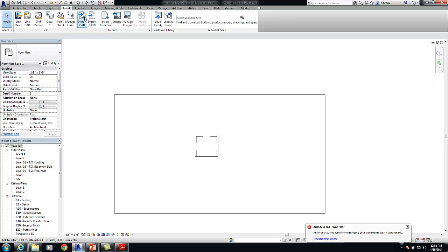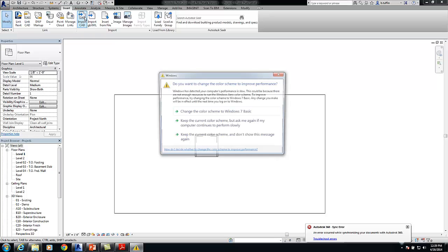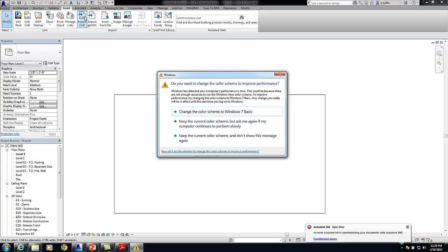Autodesk has spent quite a few years developing an interoperability between Inventor and Revit, and Civil 3D, Revit, that type of functionality. Inventor has an export to BIM. Although it's not perfect, in 2014 it's a lot better than anything I've ever seen. It will bring geometry across. It uses a shrink wrap functionality to allow you to remove your nuts and bolts and holes and your very tight radiuses. It just gives you an overall mass.